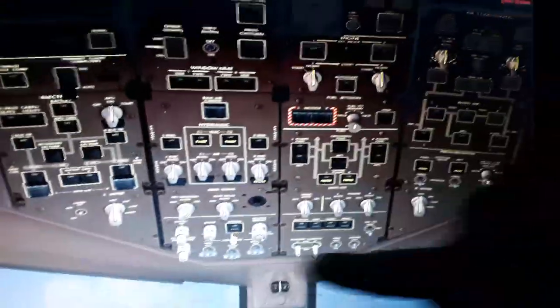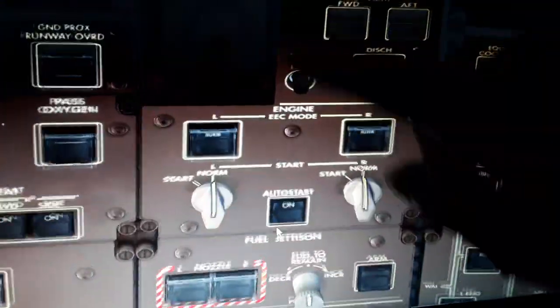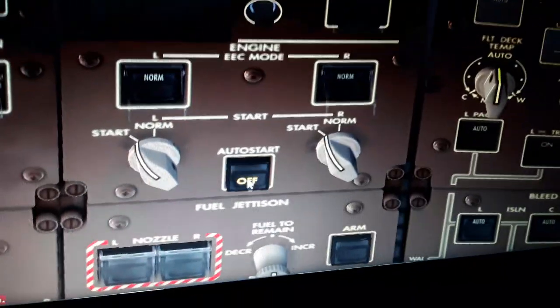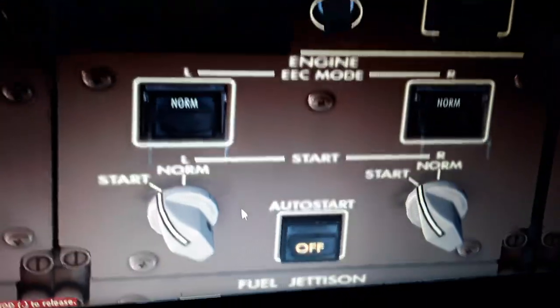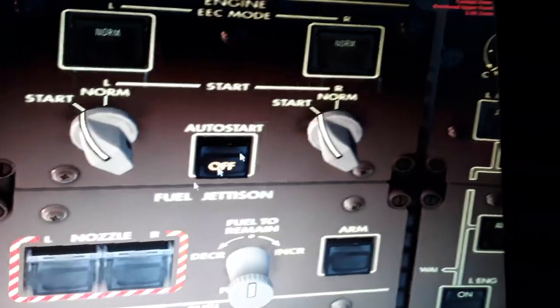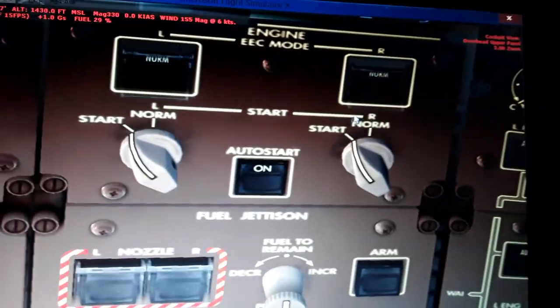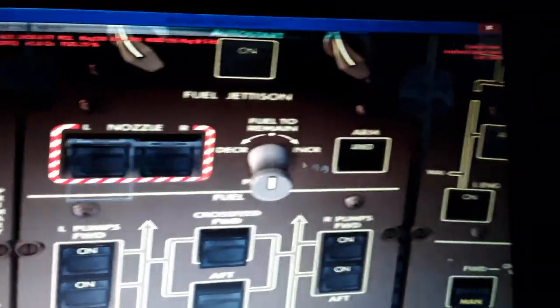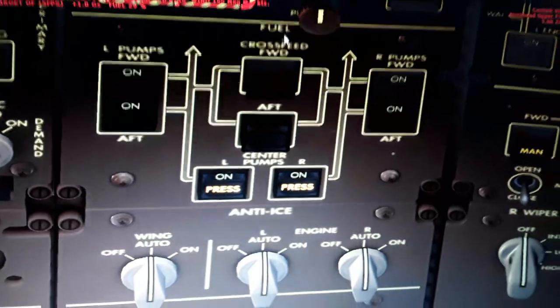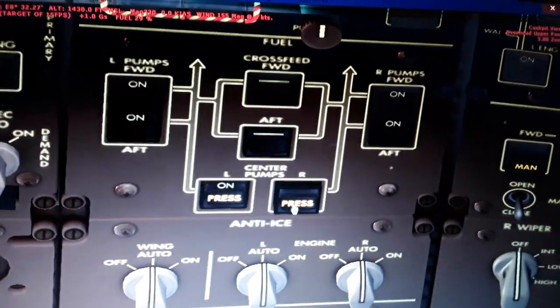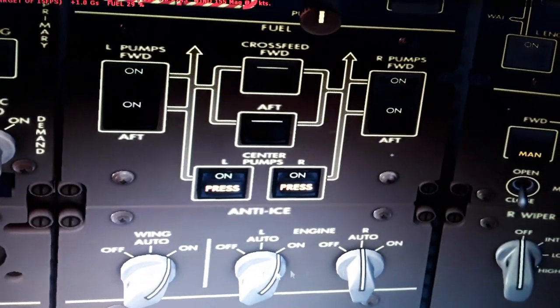We have the lighting of the aircraft and the windshield wipers. So you will see here cargo fire and APU fire, electronic engine control, auto start. I'm gonna show you the auto start of the engines after this. So we need to use that in the on. We have the normal and the alternate electronic engine control for the engines. We can dump some fuel in flight, select the nozzle. We have the crossfeed valves, the fuel booster pumps. The center tanks are empty, wing and engine ADIs.